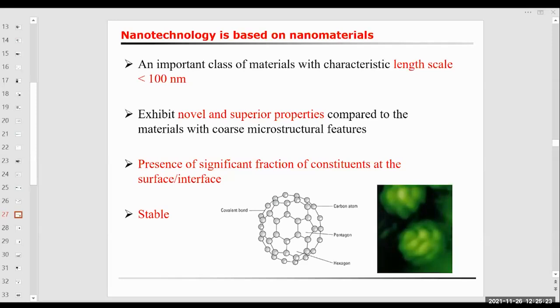And within that particle, if I use a powerful microscope and see, there are some sub-entities or sub-volumes of material locally within that particle. Each one of them is oriented in a different manner. There can be 20 such entities, and these 20 entities are called crystallites. Crystallites are smaller entities, but they are still systematically arranged. Within those crystallites also, the atoms are systematically arranged. Then that particle we call a crystalline iron particle, which is constituted by crystalline iron crystallites.